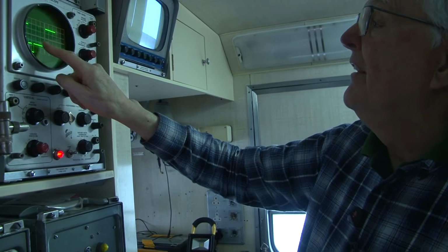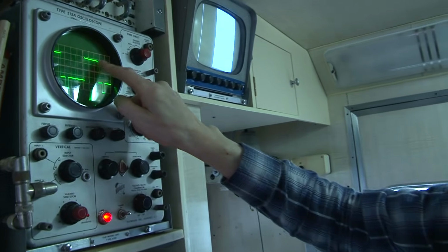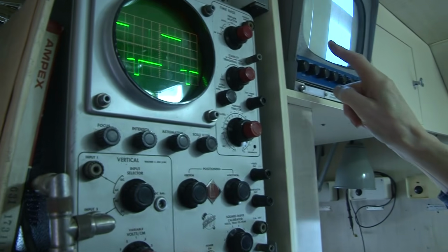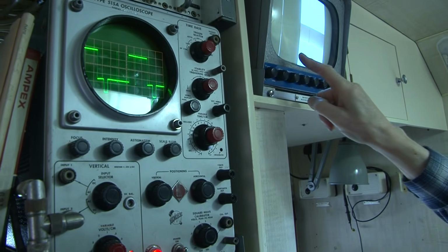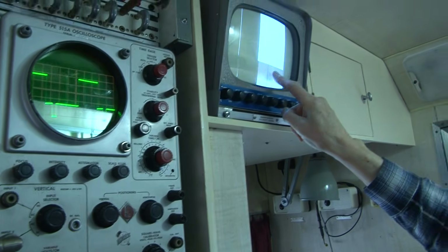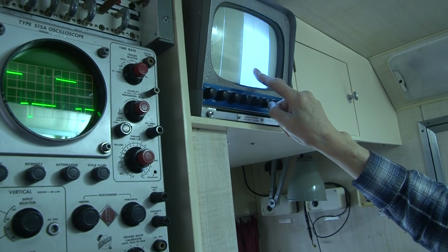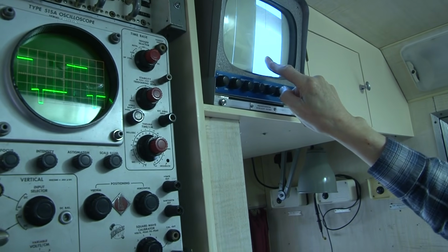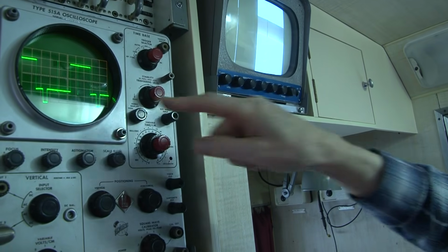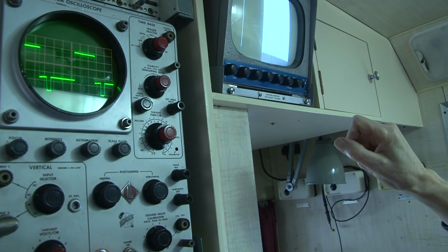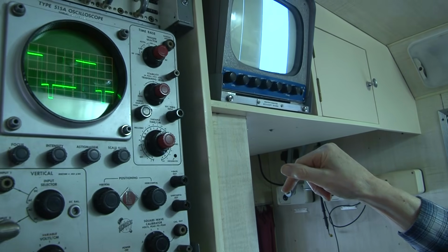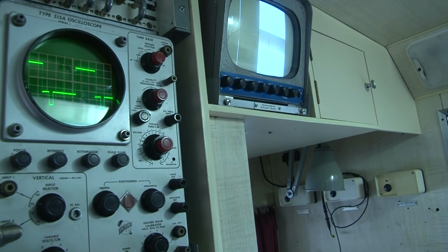And simplistically, there is a pulse and a bar. And on the picture monitor here, you can clearly see the pulse and the bar. The bar has got the negative pulse in it, which gives you the ability to look at the distortions at white level as well as black level.